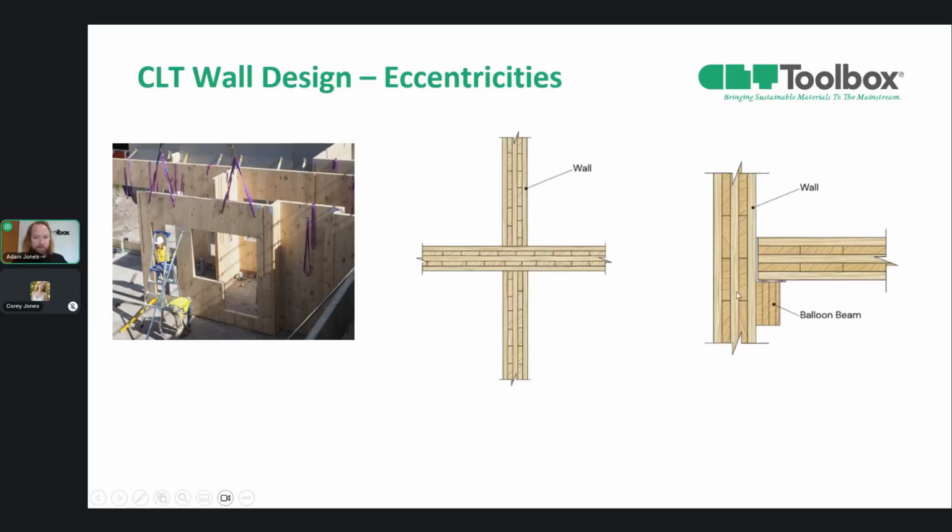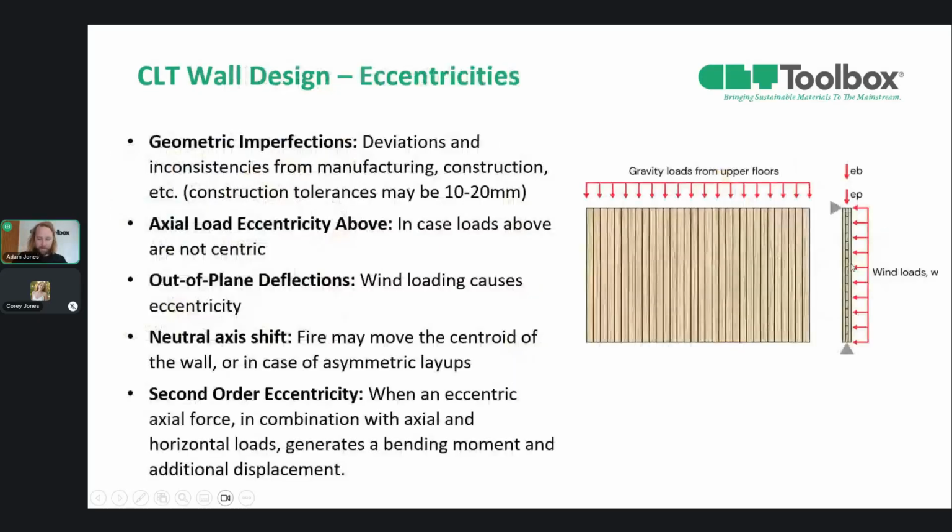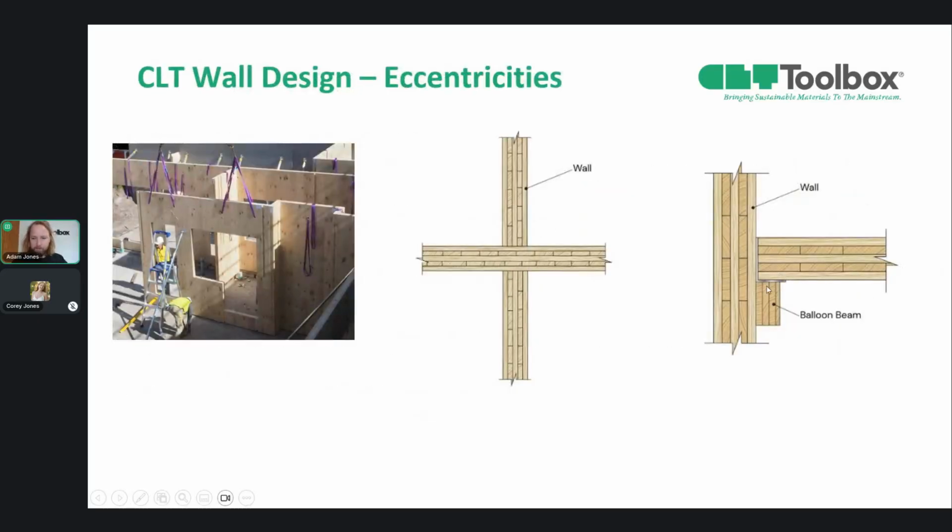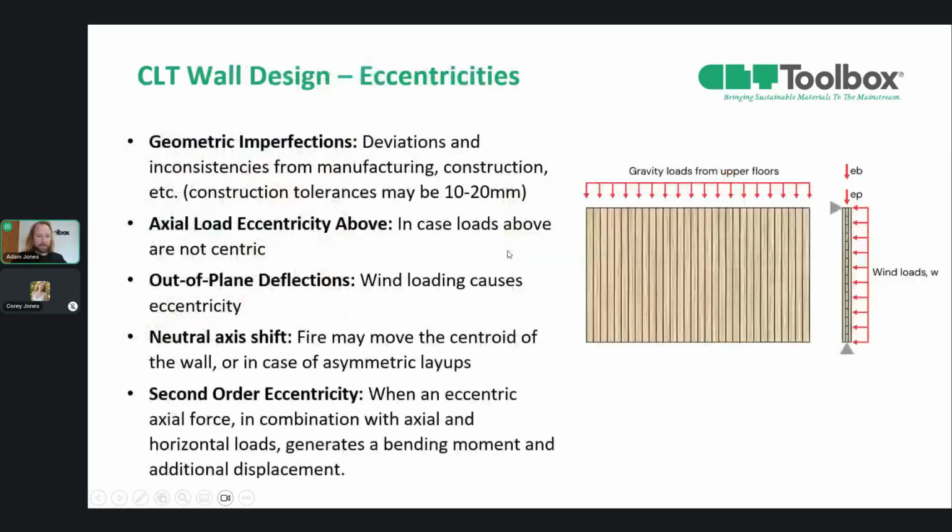The other approach is using a double height wall, for example, and with that, you've got balloon framing in this instance. So the floor will budge up and sit upon the balloon framing here, and the wall would run all the way through. So from a perpendicular grain crushing perspective, there's nothing to check here. You've got maybe an additional bending moment with an eccentricity from this floor reaction, the differences from an installation perspective, and so forth. But we're going to be looking at a platform framing point of view, and that being most common.